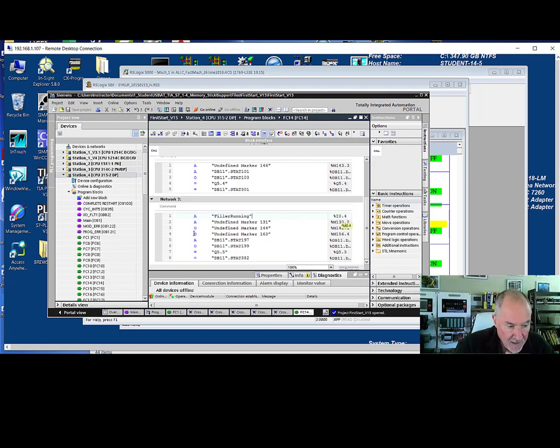if I0.4 is on and M130.2 is on, or 142.1 is on, or 156.4 is on, any one of those, and right, this data block is on. And a lot of times these data blocks are things like recipes or conditions to allow the output to come on, or data block 11, stat 199.